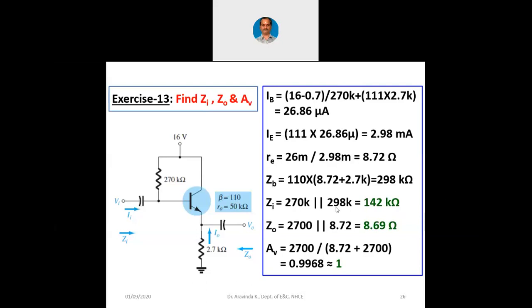So that's it now. We have seen how common emitter configuration's AC analysis is performed, and how common collector configuration's AC analysis is performed. We have seen that in the common emitter configuration we get voltage gain, whereas with common collector configuration we get larger input impedance and lesser output impedance. That way, whatever we had expected from an amplifier is satisfied by using both of these configurations.